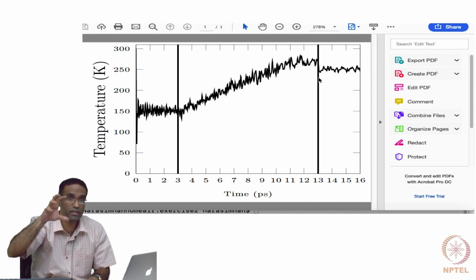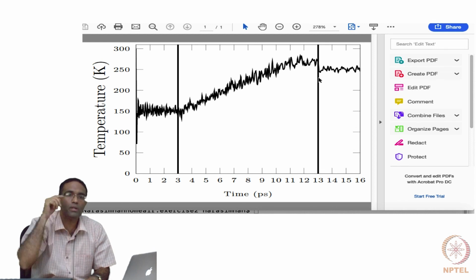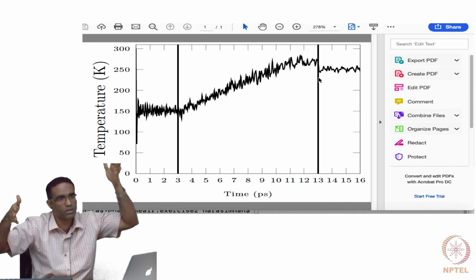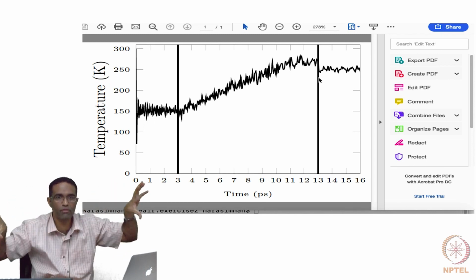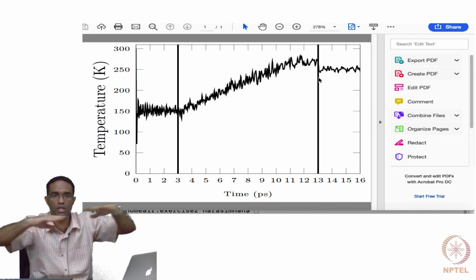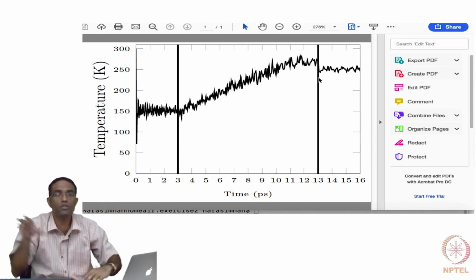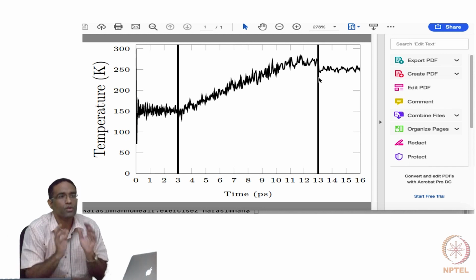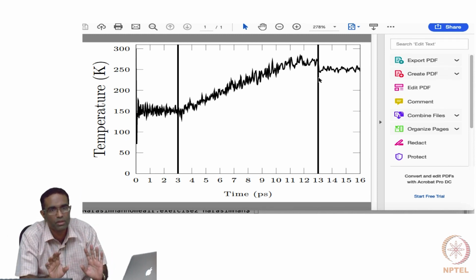If you have a body at constant temperature and you isolate it from the surroundings and then look at the temperature, it would be the same if it was actually in equilibrium with the surroundings. This bar, which had different temperatures on either side, if I isolate it from the surroundings, immediately the temperature will start changing inside, because there will be heat flow in order to make the temperature uniform throughout the system, right? So the manner in which equilibrium is checked is by isolating the system from the surroundings.